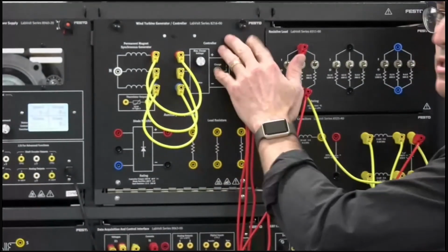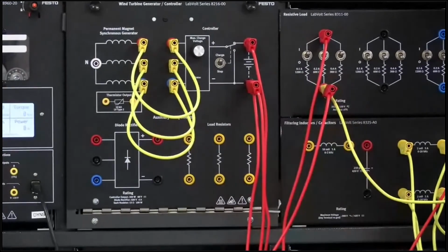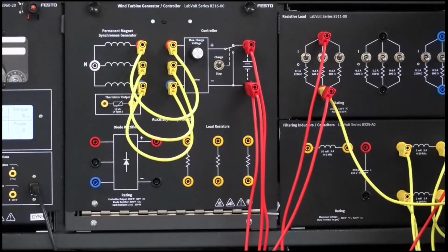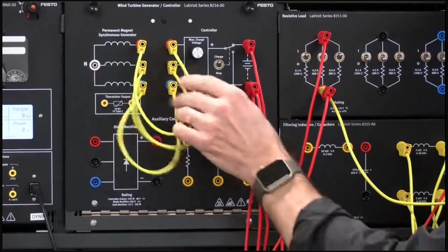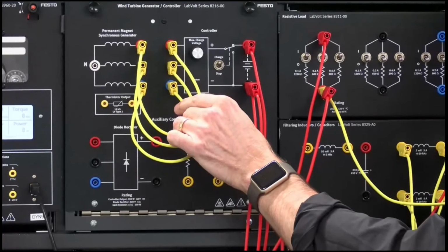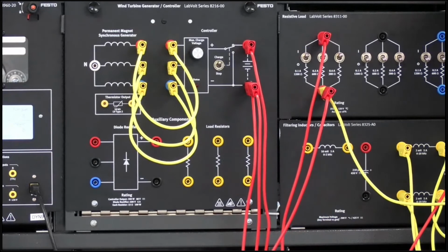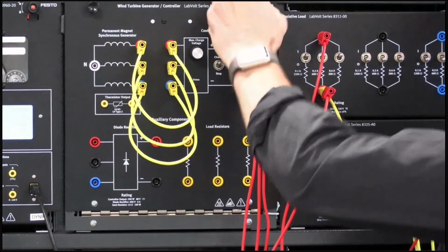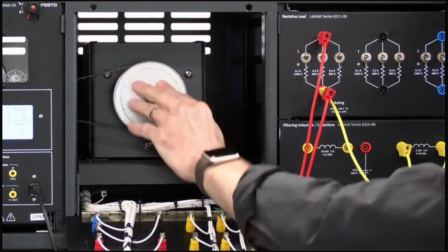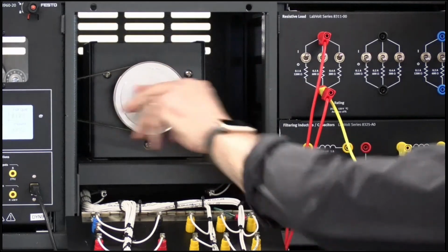Perfect. So this is the same module as you can see here, the real module. Right now it is already pre-connected for the demo I will do in a moment. But you can see that I have the 3-phase output of my generator connected to the 3-phase input of the battery charge controller. And the output of this charge controller is going, of course, to the battery lower, as we will see later on. But I wanted to show you that this generator is simply a permanent magnet generator right here in the back. And of course, we need to make it spin to produce electricity.